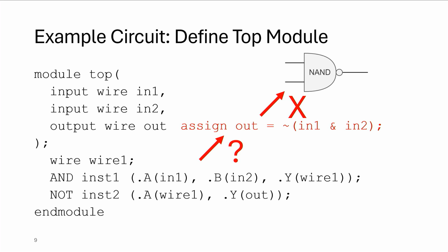Second, why are we taking the time to express this in Verilog? What does this have to do with circuit taxonomy? Well, if you noticed, when we translated the simple schematic into Verilog, we had to add several names, identifiers, and other explicit information to make sure that the schematic was being represented precisely. I used precise terms like module, instance, port, etc. to represent the exact concept I was talking about. For example, I could call inst1 a copy of the AND module, but that term isn't precise and it doesn't really reflect the meaning of it. Instead, we use the term instance, which is much more precise and doesn't leave room for ambiguity. The specific naming is a type of taxonomy, and it's exactly what we need to establish our physical design database to make sense.